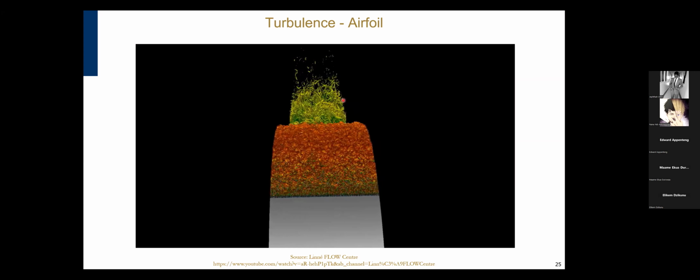When you're dealing with finite volume methods, you start with the differential balances and then convert to integral balances, so you're integrating over the control volumes. And so that leads to different sets of numerics. COMSOL Multiphysics, for instance, uses finite element methods. So those are some of the differences that you need to be aware of.